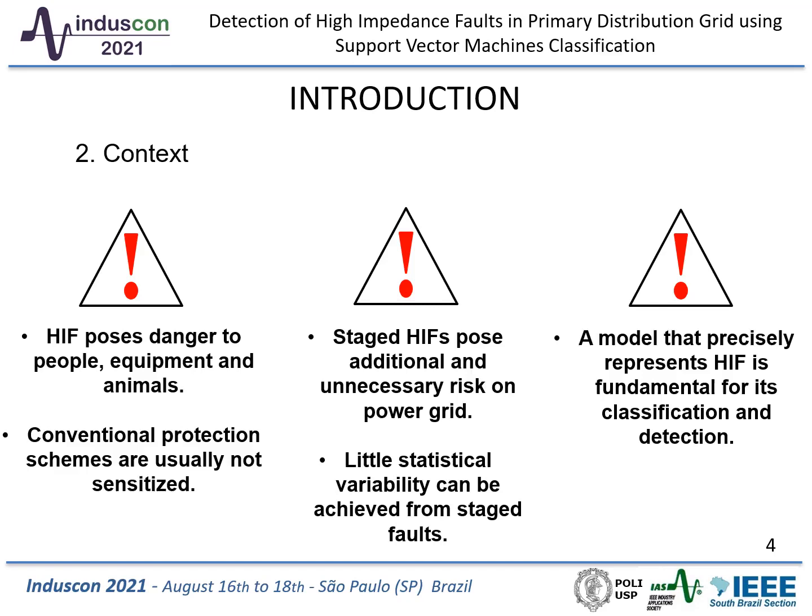One possible workaround proposed in the last 20 years was recording staged HIFs, using them to improve the overall protection relay performance. However, a series of restrictions have currently been imposed regarding the execution of these staged faults, as these can impose an additional and unnecessary risk on the rest of the power grid. Therefore, a mathematical model that precisely represents these faults is fundamental for research on HIF classification and detection.